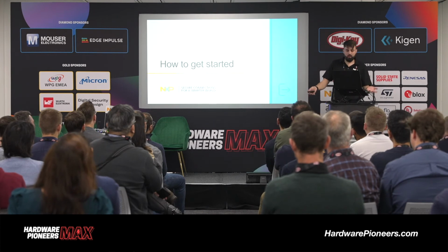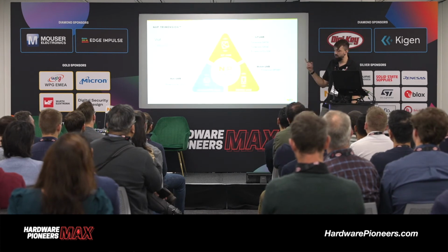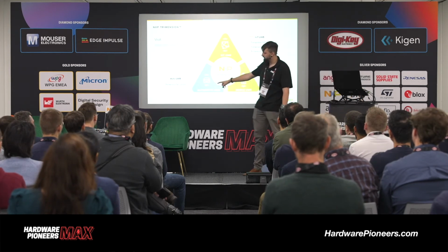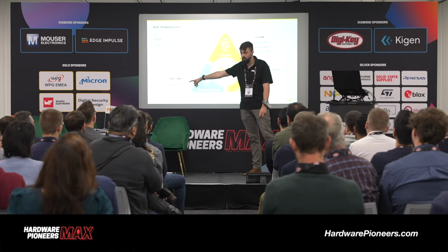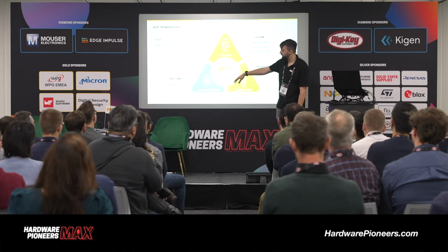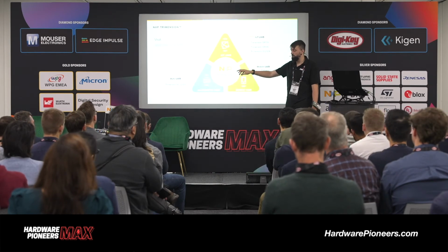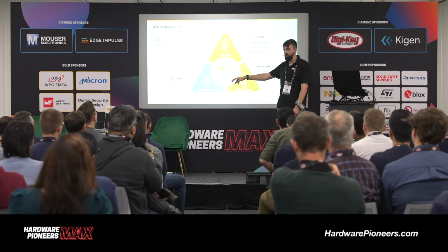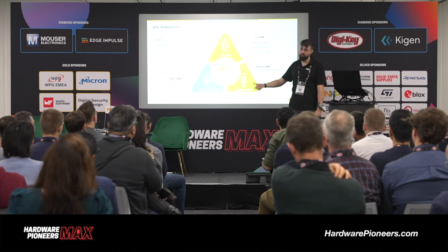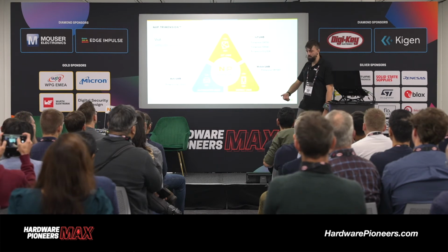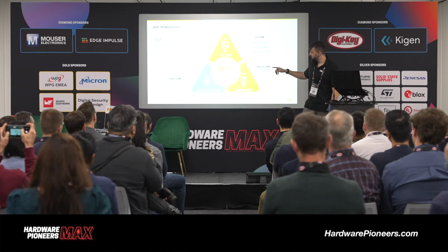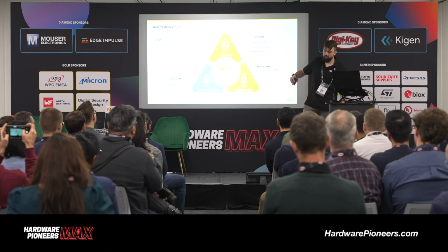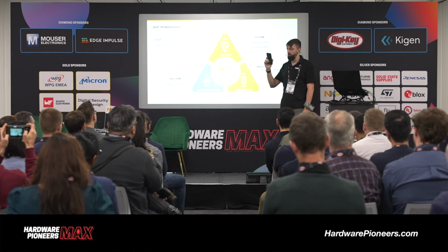So, how can you get started? NXP has a wide ecosystem of ultra-wideband products. We have on the one hand automotive chips, the NCJ29D5, which is a range of 4 or range of 5 application of the ultra-wideband chip that's already being shipped in cars. For example, BMW and Volkswagen are implementing it into their key fobs and cars for keyless go applications. On the other hand, we have the mobile ultra-wideband chip, the Trimension SR100T, which is being shipped in Samsung phones for ultra-wideband applications.